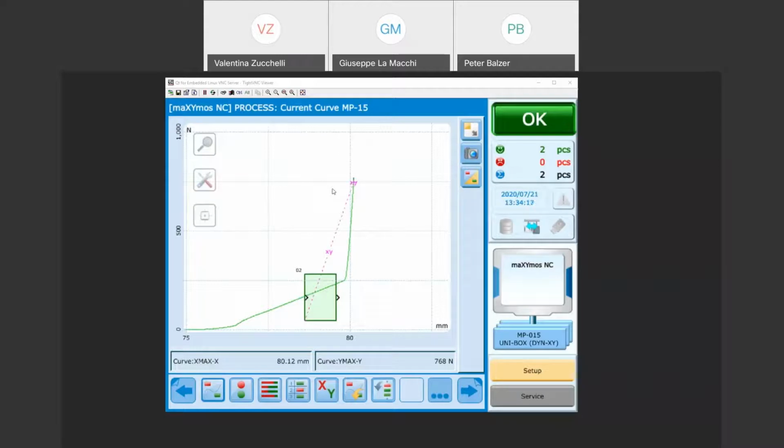There's another possibility. You can not only use the block position, you can also use in trigger Y. I would like to show you the curve first. I need to remove the papers. Now I've referenced it to trigger Y in the next program. So now you see trigger Y means a threshold, a force threshold in between of the curve. Let's have a look at the setup.